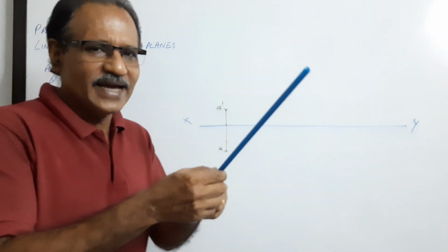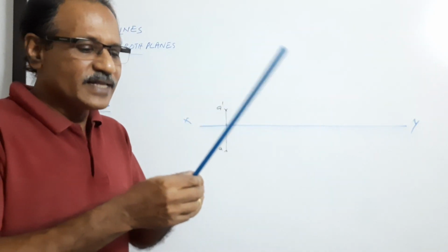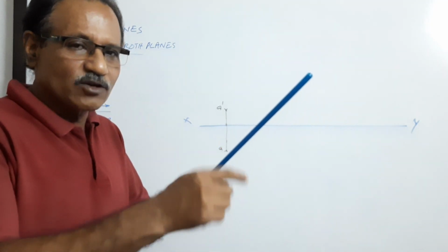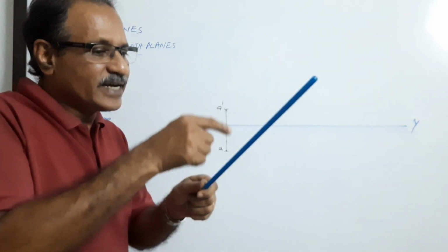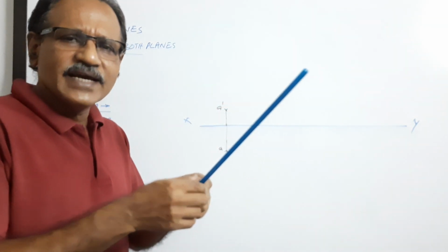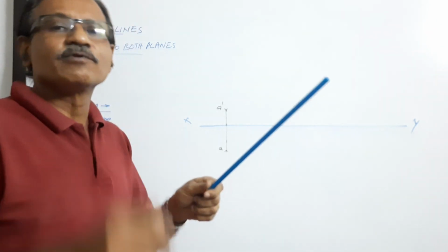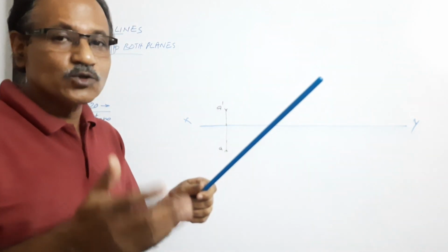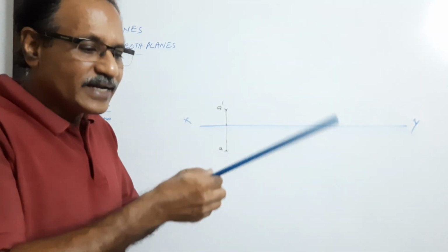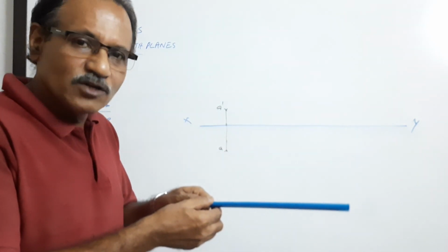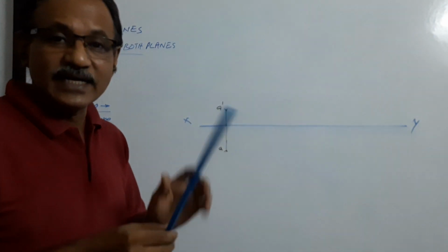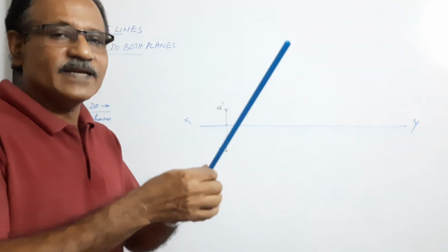This is the line. The line is inclined. The line is 100 mm long. The line has got the end A in a specific position. The line makes an angle of 40 degrees to HP and 30 degrees to VP. Since the line is inclined to both planes, neither the plan nor the elevation give true length. To see true length in the elevation, the line needs to be parallel to VP. It is not. To get the true length in plan, the line needs to be parallel to HP. It is not. So neither the plan nor the elevation give true length. That is our difficulty.